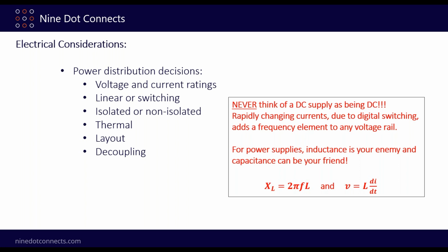And so inductance is your enemy, and of course capacitance, one of its main purposes in life is to oppose a change in voltage. When voltage starts to drop, it gives up some of its charge to keep that voltage up. So that's why decoupling is very important.